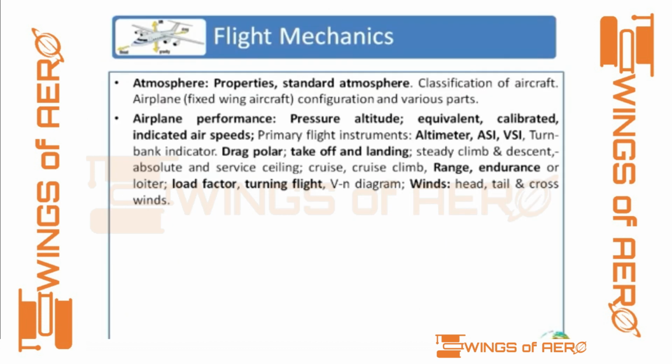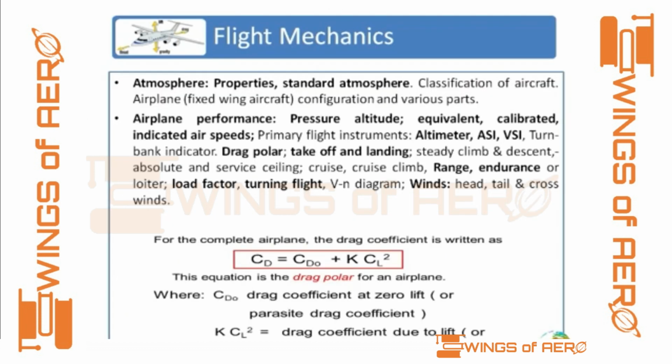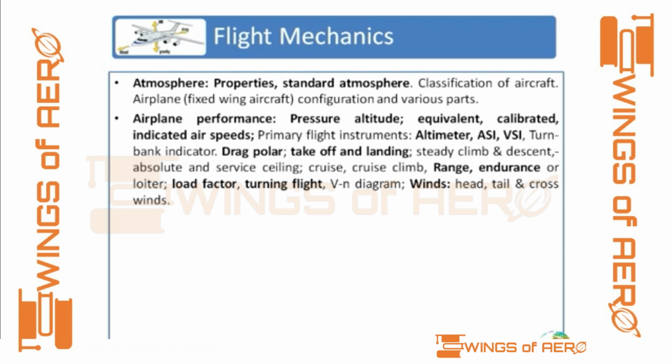Then comes the drag polar. Definitely a question will be there on the drag polar equation. You should know the basic equation of a drag polar, its characteristic property, and graphical representation. In drag polar you will have two basic conditions, that is the minimum drag condition and the minimum power requirement condition. In each case, what are the formulae, and how the velocities are related to each other. You better refer to Aircraft Performance by J.D. Anderson for this topic.